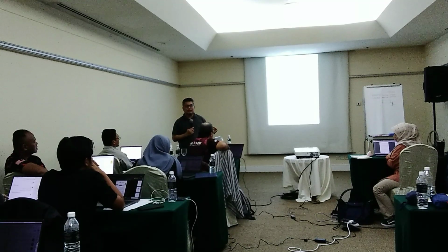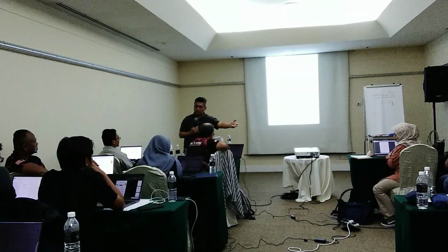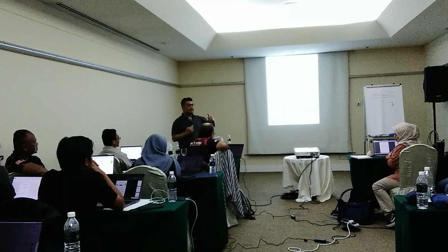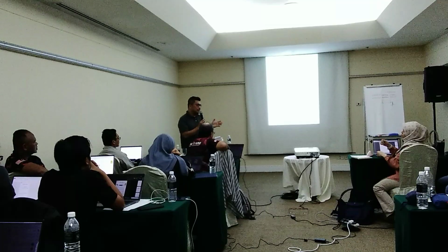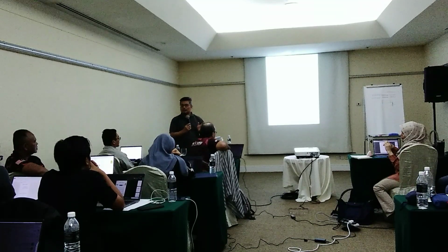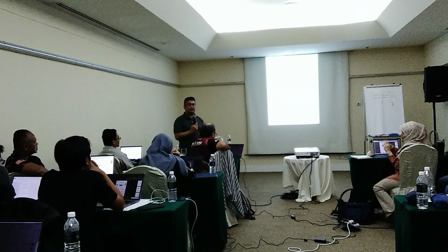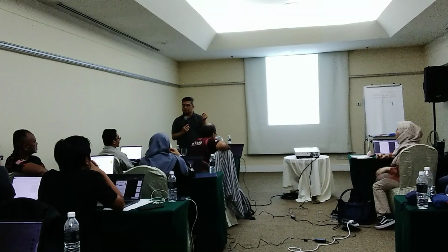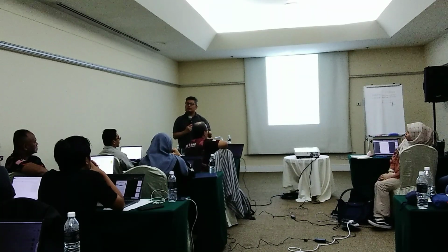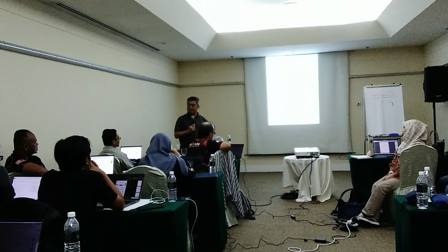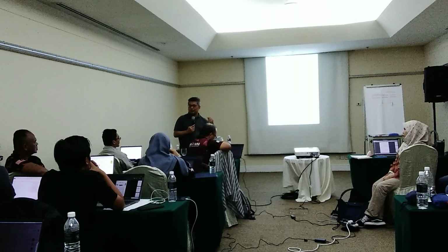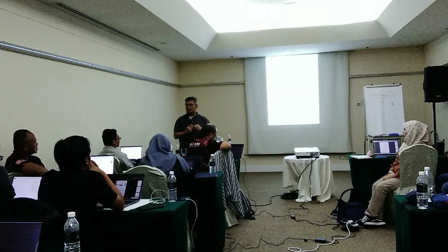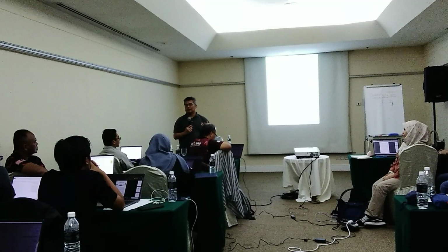Because normally it must come from the previous process, but instead it came from the later process. The machine's location is very close, and they managed to identify that because the metal chip that created the defect was only produced in process number 4. That's how they determined that. Without that kind of detailed analysis down to the material type, they would not be able to understand where this dust came from.